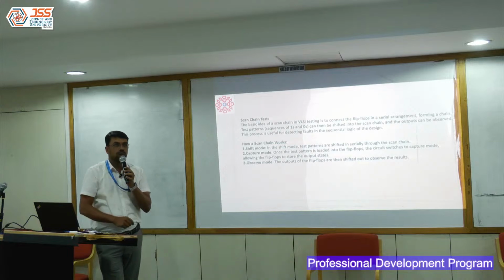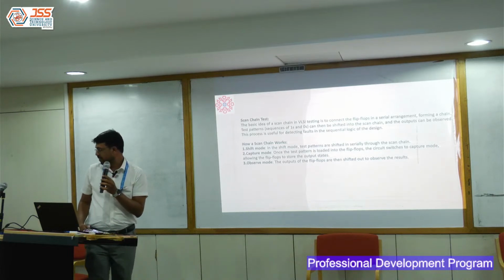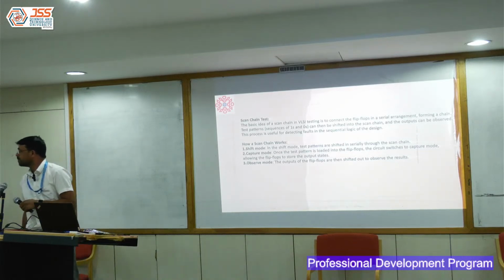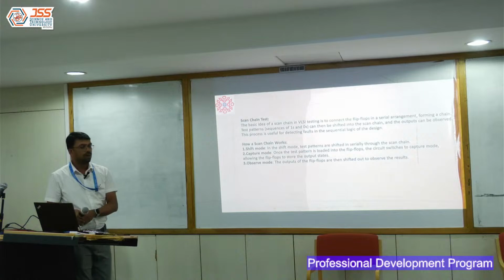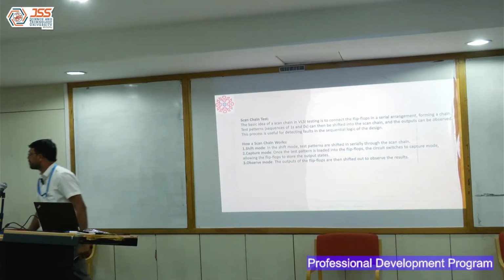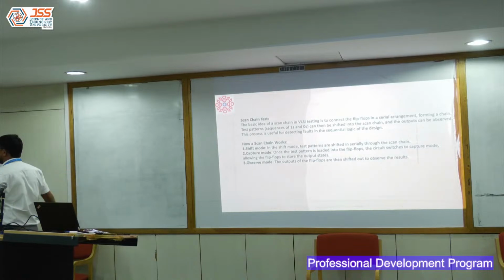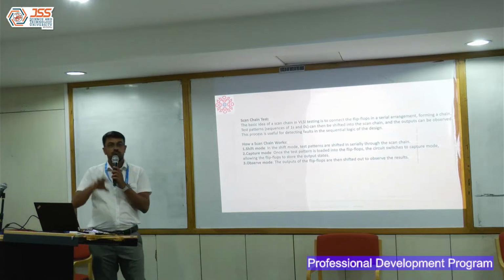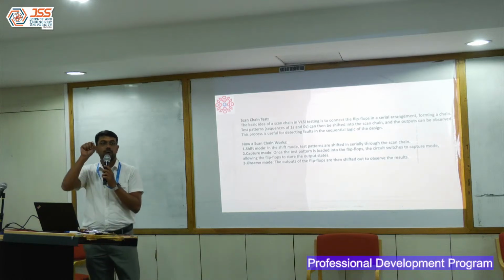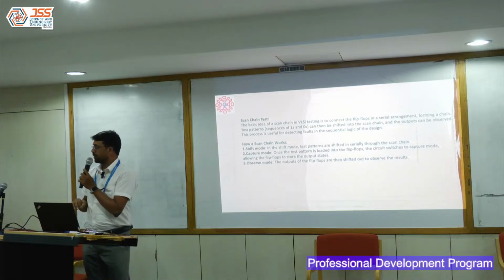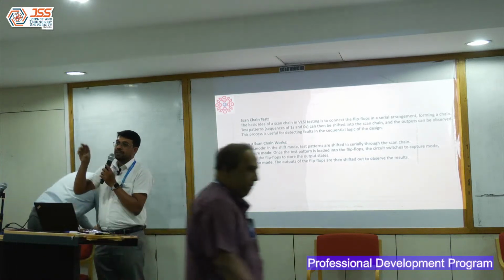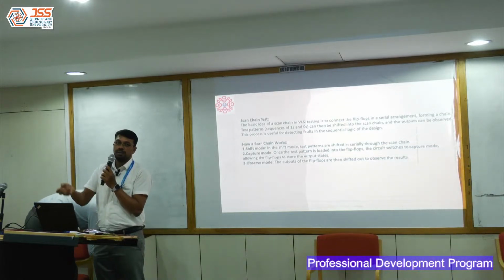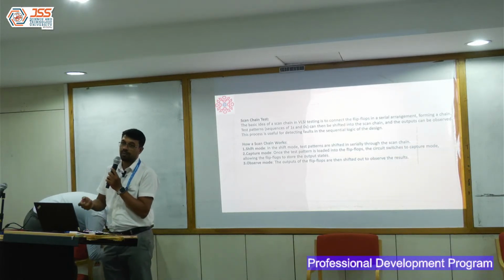Can I write on the board? Okay, I'll try to explain. Basically, you know a D flip-flop. A D flip-flop has one D input, clock and Q. I'm leaving out the set, reset and all just for the sake of understanding. Now, how can I make this a normal regular flop into a scannable flop? I'll just write and show you.